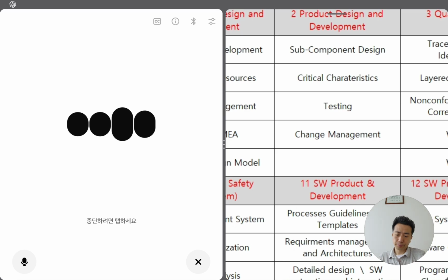Great question, David. This is very practical and shows you're thinking like a supplier preparing for an audit. Let's go step by step. How critical and special characteristics are marked. 1. On drawings, usually marked with a symbol next to the dimension or feature. Common symbols: CC inside a triangle or circle for critical characteristic; SC inside a diamond for special characteristic. Sometimes just a flag note or character linked to a legend explaining the meaning.